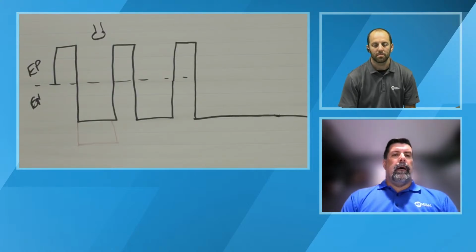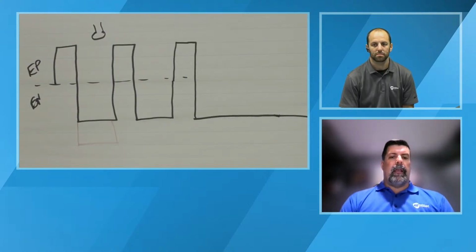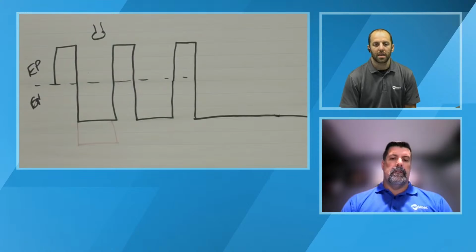So I've been in some shops where they are actually utilizing anodized aluminum for resistance to corrosion and other properties. Is there anything that you'd need to do differently when you're welding on anodized? Yeah, so anodized aluminum, if we think about what anodization is, so aluminum, we use alternating current because it has that skin of oxides on the surface.